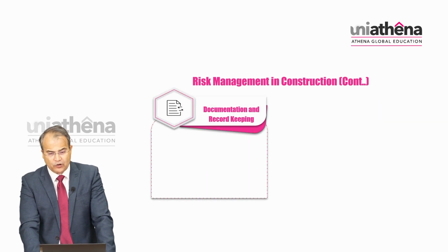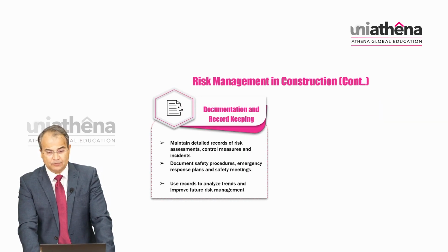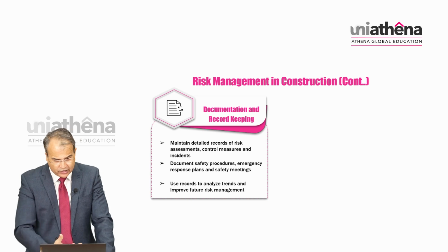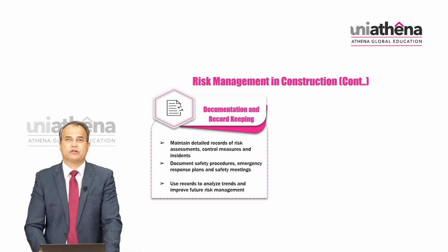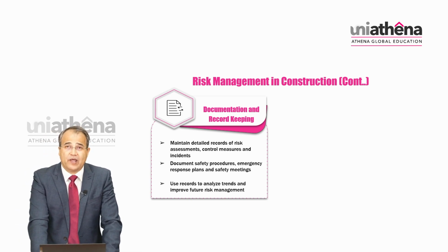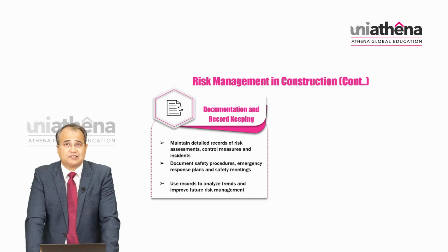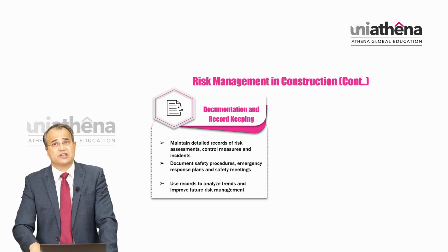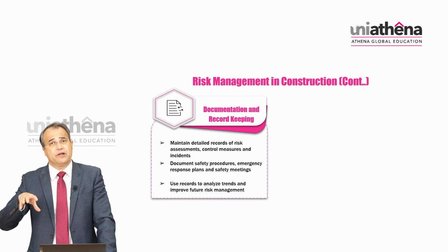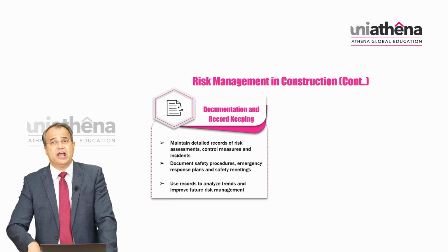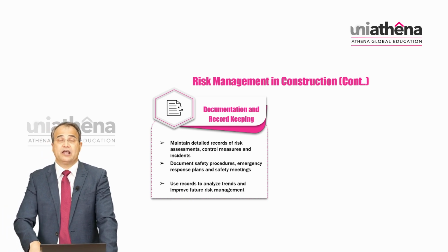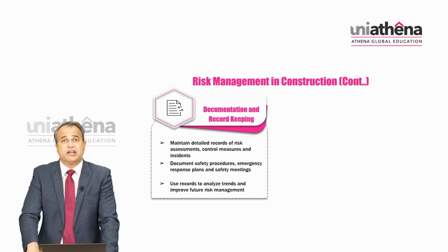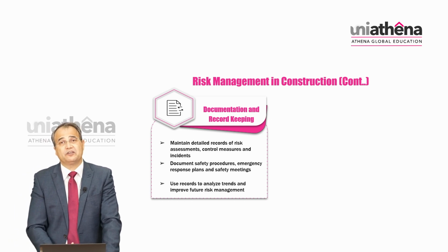We also need to look at risk management in construction in terms of documentation and record keeping. Very, very important to have. Remember that a project can last 3 to 4 years, sometimes longer. You need to understand that each and every reported incident, each and every investigated incident, and each and every near miss needs to be documented, and documented properly.